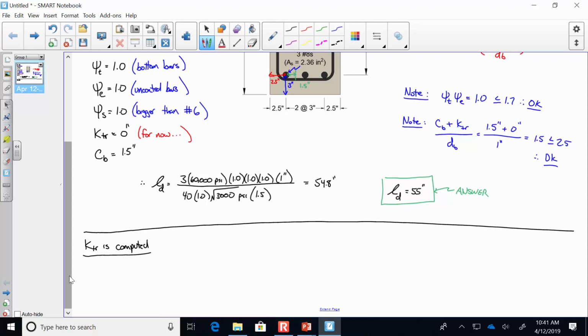Does that mean for every problem that we've done so far, we assume the development length is good? Yes, that's a great question, and the answer is yes. This is kind of a different question, but development length only takes place for cantilever beams, right? No. It's just for any bar in any situation. Okay. So this beam would not be cantilever. This would be a simply supported beam. So what would the rebar go into on a simply supported beam? I'll show you that here in a second.